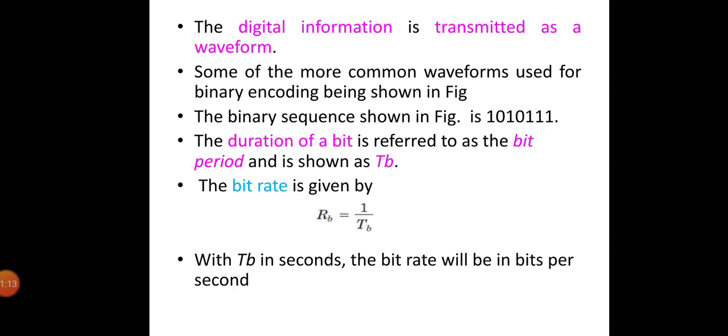Analog signals such as speech and video signals may be converted into digital form through an analog to digital converter. A particular form of A to D conversion employed is known as pulse code modulation, and some of the sources may use medium data rate PCM, and you can also use an analog to digital converter with a bit rate reduction, that is, digitized video can also be used.